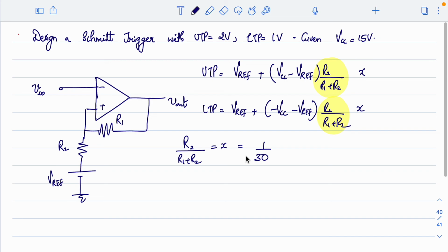So this is possible even in the other case. By specifically choosing a reference voltage, we can switch the threshold points both towards positive or both towards negative, depending on what reference voltage we take, right? So this is the third category I was mentioning, where you will have different threshold points, but both with the same polarity. So these are the various types of Schmitt trigger designs, and probably we'll wind up today's class here. If you have questions from this, please do ask.